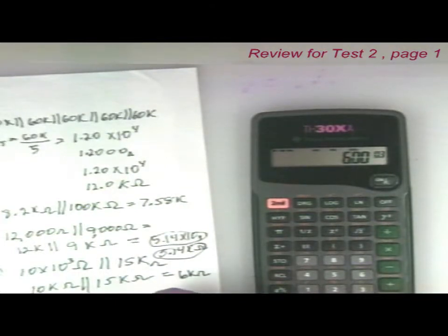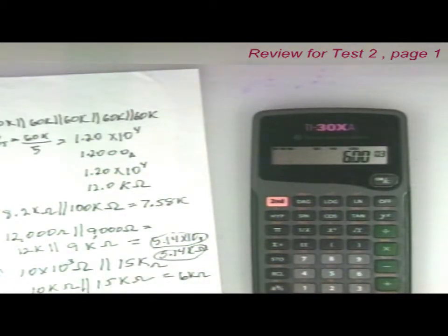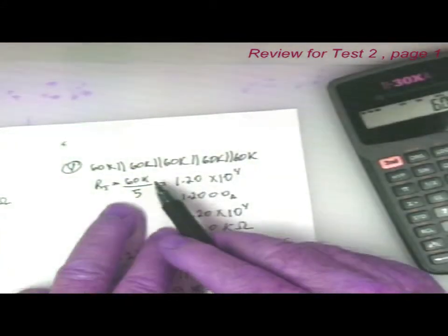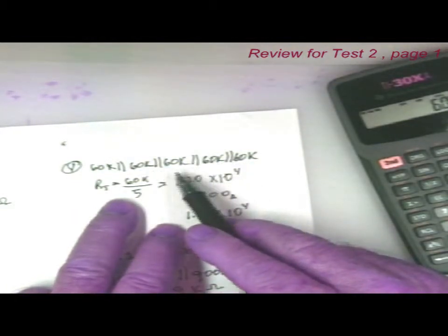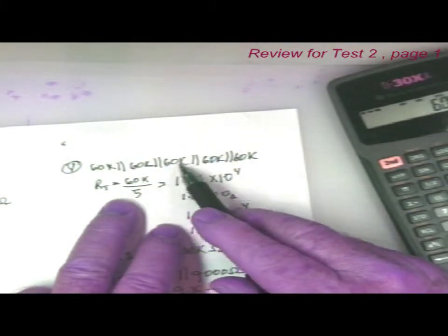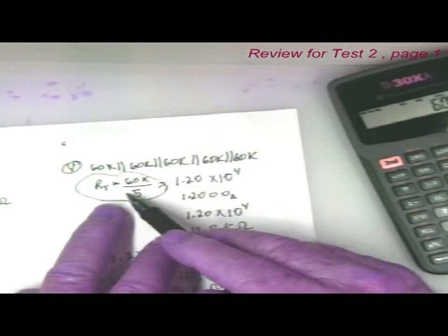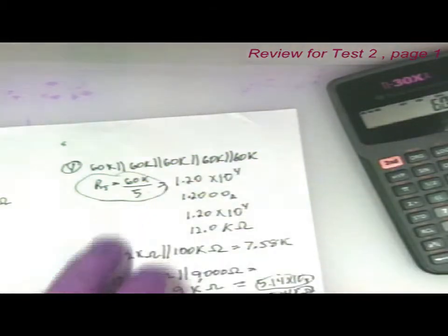But again, why I like the reciprocal formula, it'll solve any of these parallel problems with any number of resistors. This product over sum, though, we can only use on 2 resistors. Why remember another one that you don't need to? I do like the one here, though, where they're all the same, especially if you have a long number of resistors. If you only have 2 or 3, I'd use a reciprocal. But if you have more than, say, 3, it doesn't hurt to use this formula here, where RT is equal to one of the resistor sizes divided by the number of resistors.